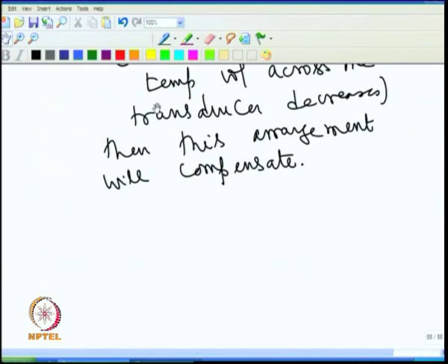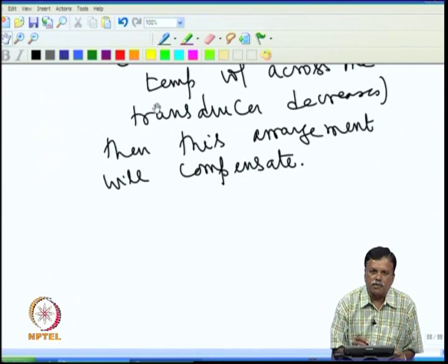So, in this case the transistor drift is used for our advantage, and this kind of application is common in the real world, because the transistor is a very dependable temperature drift element, as the base emitter voltage changes accurately by 2.2 millivolt per degree C. This kind of accuracy you will not get in a thermistor.